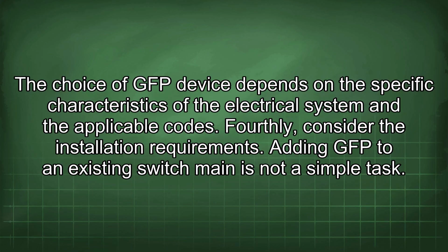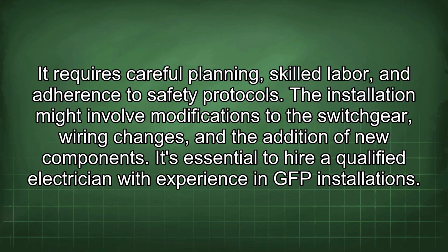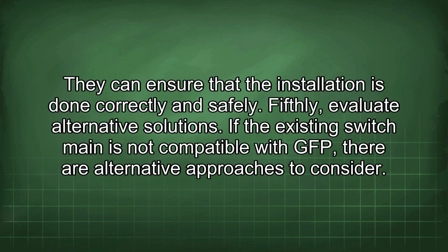Fourthly, consider the installation requirements. Adding GFP to an existing switch main is not a simple task. It requires careful planning, skilled labor, and adherence to safety protocols. The installation might involve modifications to the switchgear, wiring changes, and the addition of new components. It's essential to hire a qualified electrician with experience in GFP installations. They can ensure that the installation is done correctly and safely.